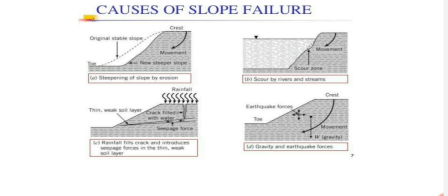See, one more thing is there. Sudden drawdown case. That is, if there is a sudden drop in level of water adjacent to the slope, this can cause a seepage force within the water present in between the particles made up of the slope. In between the particles of sand made up of the slope. Due to this seepage pressure, soil piping can occur. That is another topic.